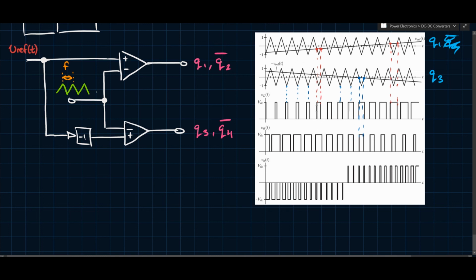What I mean by that is that because of the way these switching pulses line up, you end up with a higher frequency sort of sampling. And I put sampling in quotes, because we're not technically sampling, but I guess the PWM is kind of sampling. So in that case, it's easier to filter everything when it's at a higher frequency.